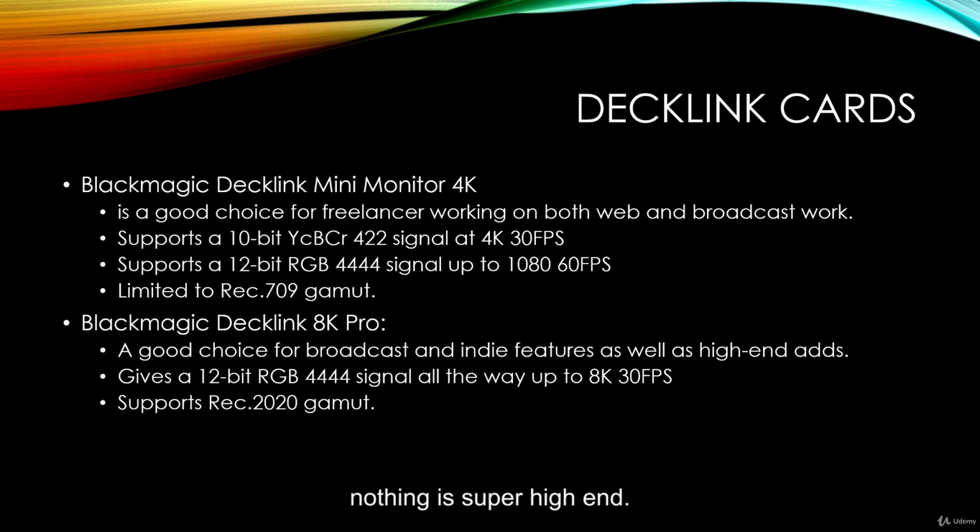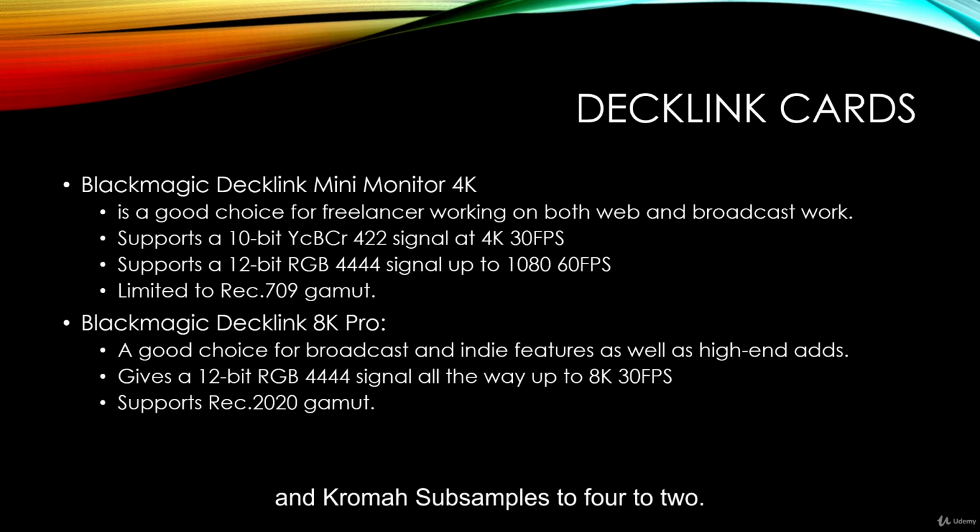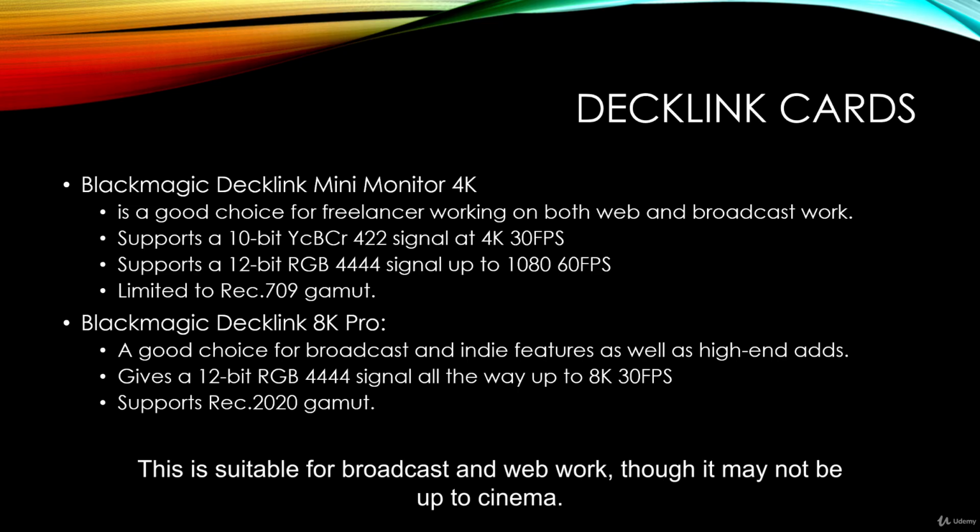There's really just one DeckLink card to consider if you're just working for broadcast and web and nothing is super high-end, and that is the Blackmagic DeckLink Mini Monitor 4K. These are relatively inexpensive and will support 4K material up to 30 FPS progressive in 10-bit and chroma subsampled to 422. This is suitable for broadcast and web work, though it may not be up to cinema.